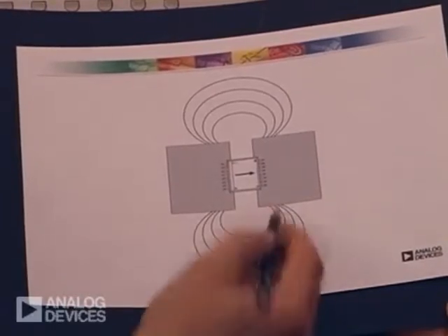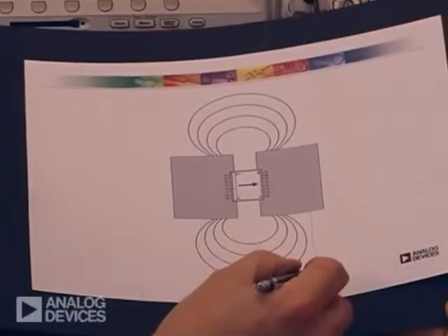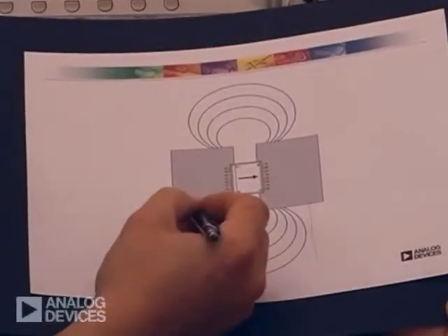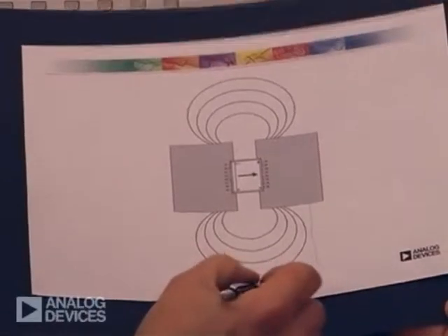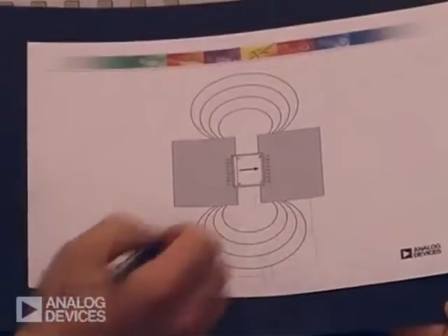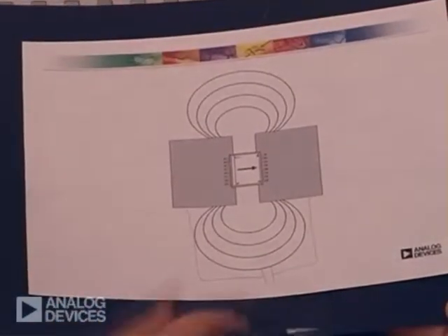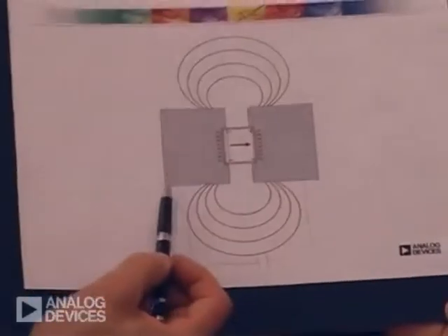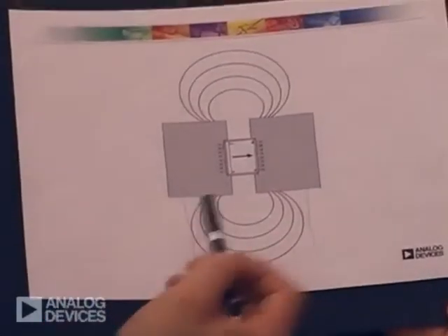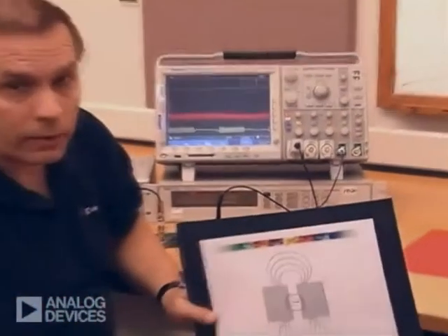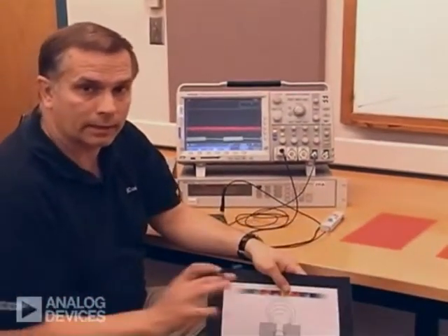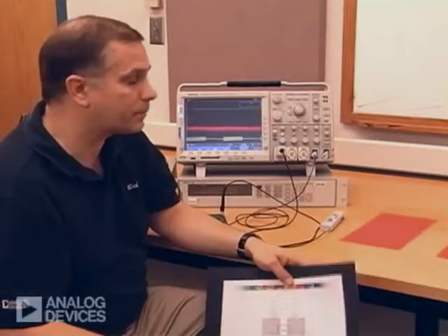And the easiest way to do that is to give the image charge currents that are being pushed across this barrier a path back to the primary, which basically shorts the dipole out and removes a lot of the emissions. In order to do this, it requires board layout modifications be made right at the beginning of the design process.